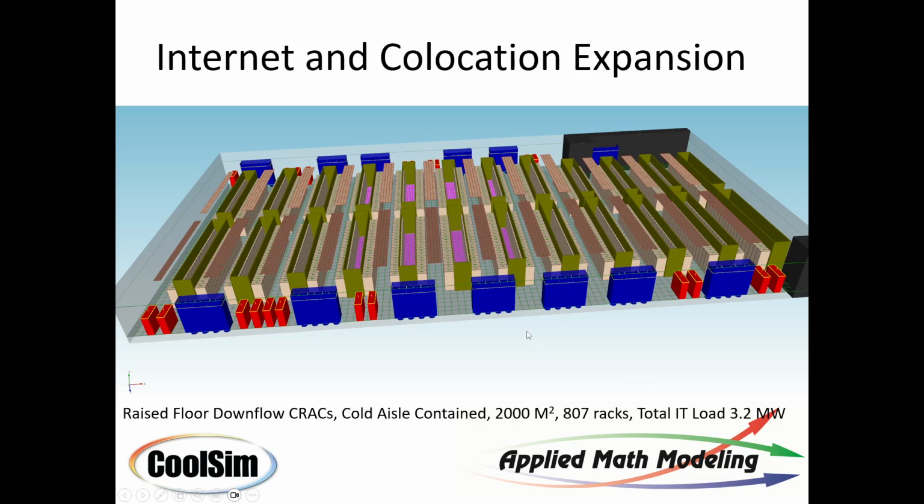You notice that the cooling units themselves have extensions on them that go up into the ceiling. So they're sealed up against the ceiling plenum. The return takes place in these grills. So the hot air comes out of the servers, up into the grills, back around to the cooling units, and back down into the floor. Cooling units is where the heat, of course, is dumped.